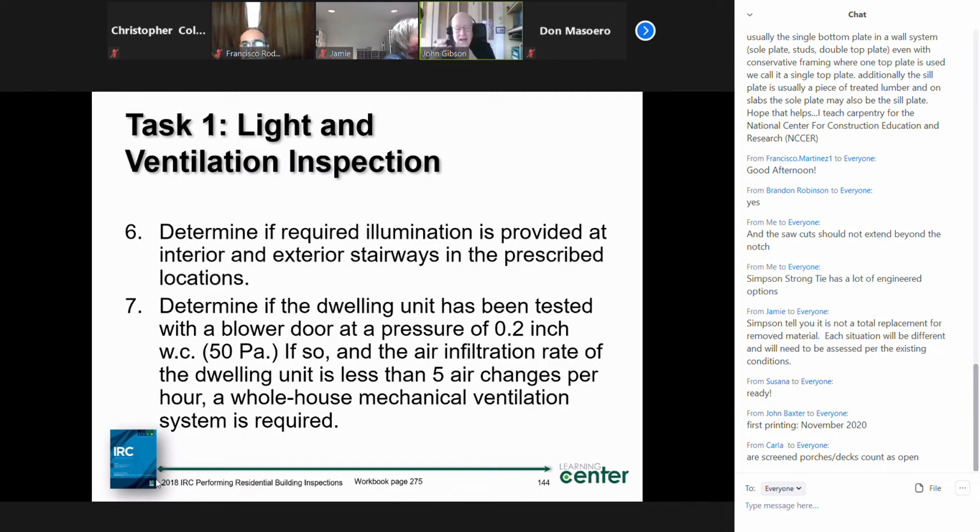And if my house is losing more air through gaps and openings than what is permitted from the energy conservation section, which for all climate zones it's 5, and for certain climate zones it's going to be 3 air changes per hour. And if I exceed 5 in terms of tightness, it says your house is too tight. So you have to have a whole house mechanical ventilation system.